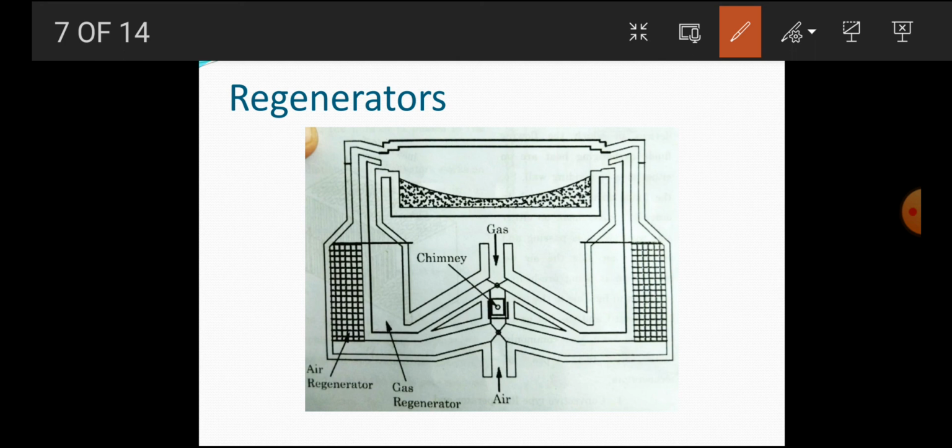Also, accumulation of dust and slagging on the surfaces reduces the efficiency of the furnace and it becomes old. So the main application of such type of regenerator is where the exhaust temperature is very high, such as glass and steel melting furnaces. So that is the main goal of a regenerator.